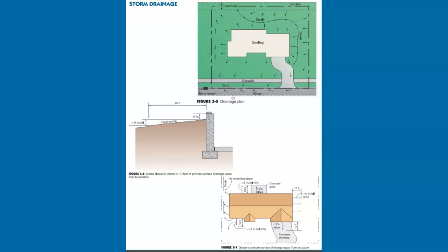In many cases, a drainage plan is already established as part of the master plan for the entire housing development and additional plans are not necessary. Other jurisdictions may require only some indication of the direction of drainage flow on the required site plan or may verify drainage on site visually without measurement at the time of inspection.